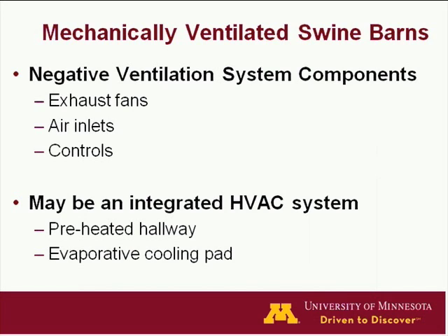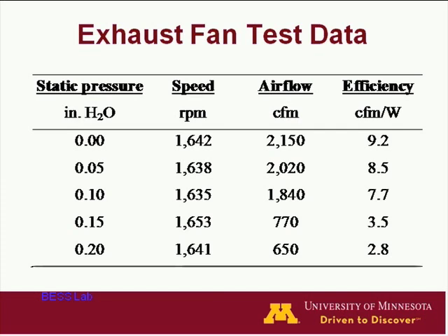In mechanical ventilation systems for swine barns, we really have three components of the system: the exhaust fans, the inlets, and controls, and this may be integrated also with heating, ventilating, and air conditioning systems. There may be some preheated hallways, like in a nursery building or farrowing, and in some particular cases for sows, there may be some adaptive cooling systems used.